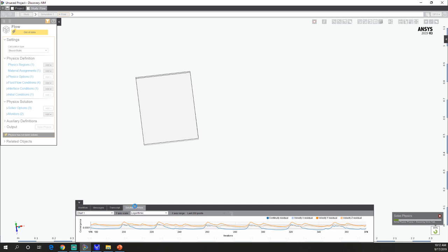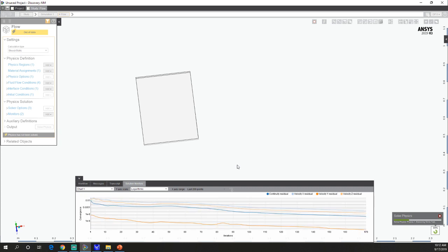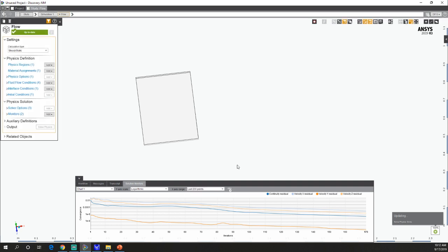Another tip when you start wind loading is I highly recommend you start with something like a slice here, because you can see how fast the simulation goes. You can really try a lot of different ideas and options to fine tune your settings before you tackle the full model. Sometimes people try to tackle the full model too quickly, and that causes issues.